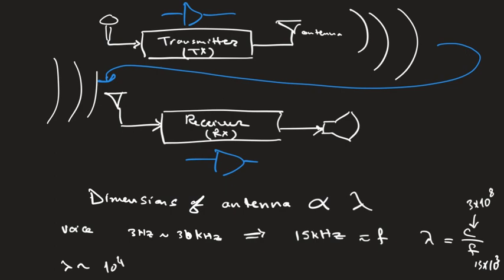So that probably introduces another component here, which is going to do modulation. Since I already changed the nature of the signal and brought it to a different frequency range, eventually I want to listen here to the original signal, the actual voice. So I have to bring it back down. Once I add modulation at the transmitter side, I have to add a corresponding demodulation component at the receiver side. And things will go like that. So there are other challenges. To address them, you need to add something in the transmitter, but because that is going to change the nature of the signal, you need to add something to counter that in the receiver, right?